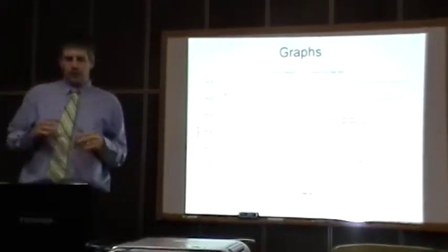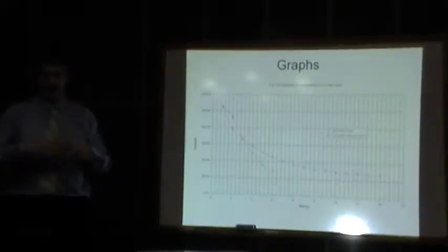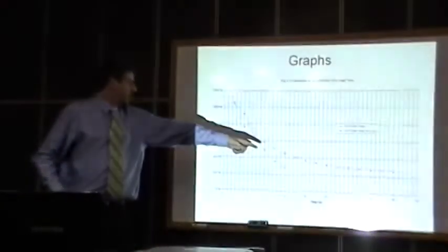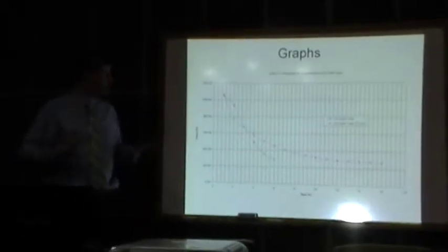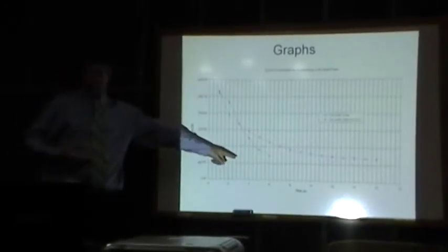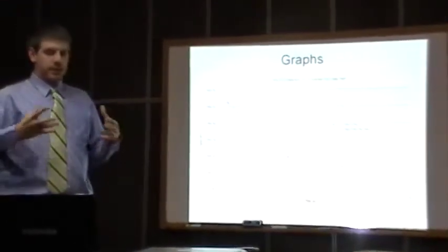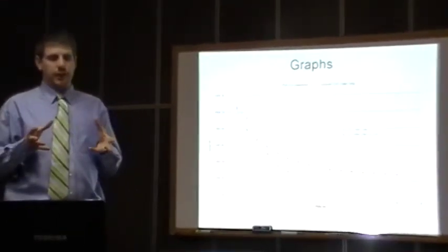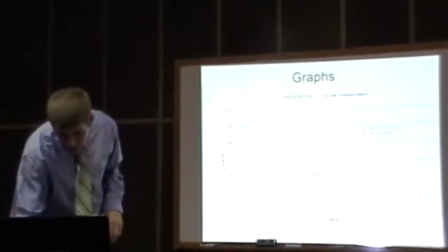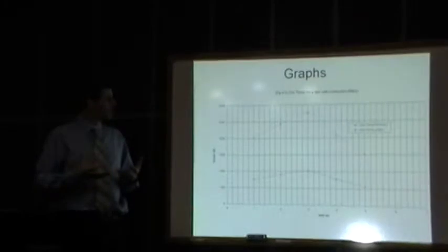This is a graph of the CO2 outlet temperature assuming axial conduction versus infinite conduction through the beryllium. As you can see, we have our nice gentle curve for assuming infinite conduction through the core, and at 7 seconds we have a very drastic change in the outlet temperature of the CO2, as expected, since in the axial conduction the top cools off fastest, so that the CO2 is taking all the energy out of the lower sections of the core.